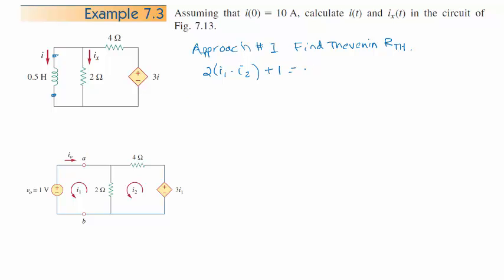And there are no other resistive components over here, so you only have that middle component. That's loop 1. From there we get I1 minus I2 equals minus 1/2. No problem there. Then we do the same thing for loop 2, and you get